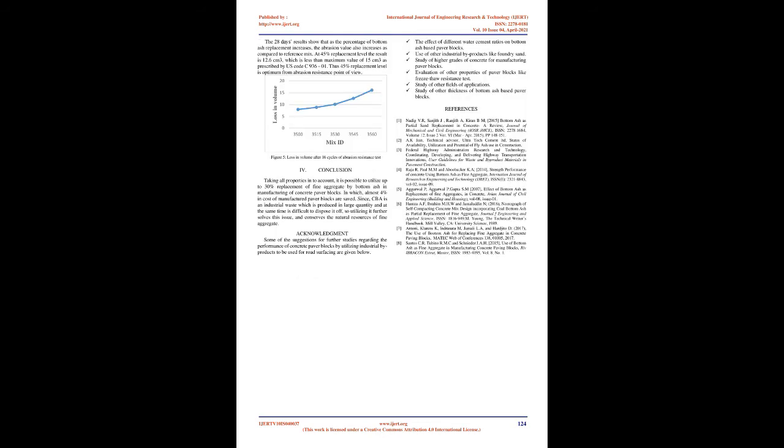The results of compressive strength of paver blocks with and without CBA are discussed as under with varying ages of 7 days, 28 days, and 56 days. From the above results it is seen that the compressive strength of paver blocks with age increases for all CBA replacement levels. The compressive strength at 7 days is found to be 80 to 90% of compressive strength at 28 days, and the compressive strength at 28 days is found to be 94 to 99% of compressive strength at 56 days. As the substitution of CBA by weight of sand increases, the compressive strength decreases.